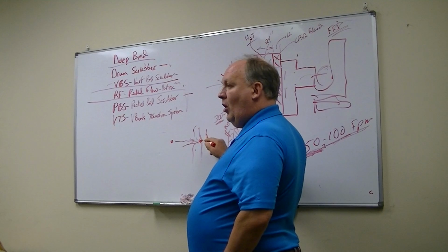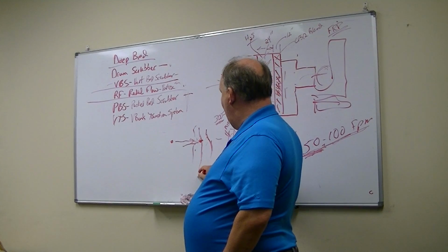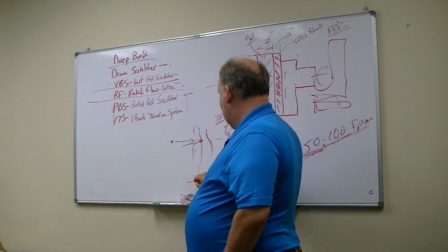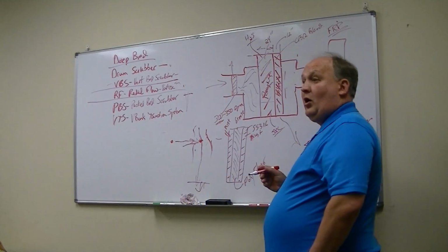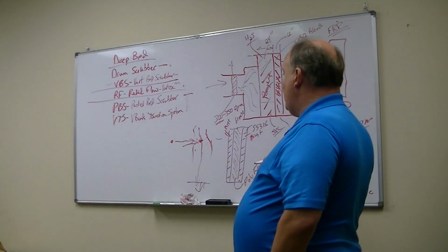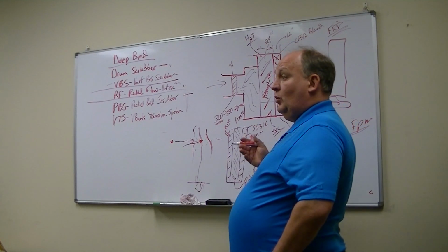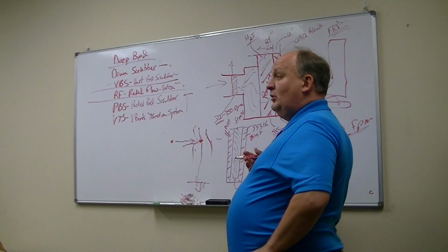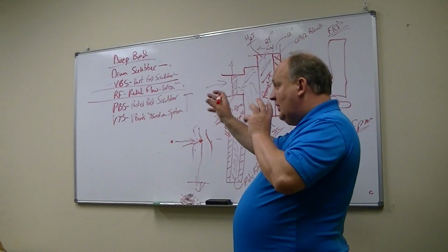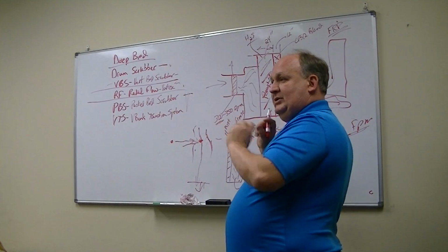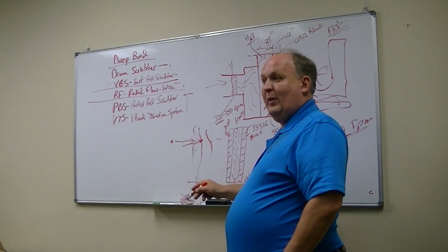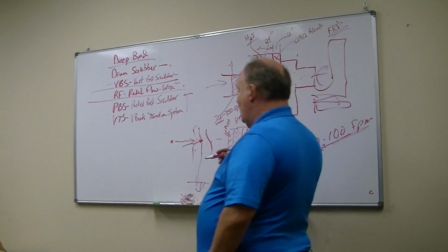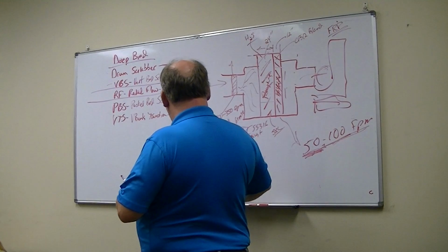Finally it makes a larger droplet, and they drain down the fibers. There's a drain at the bottom of the mist filter housing, and the water comes out. So that's how the mist filter works. It's on the principle of impingement, collecting all those little fog droplets, and once they collect, they get large enough to drip out of the system.